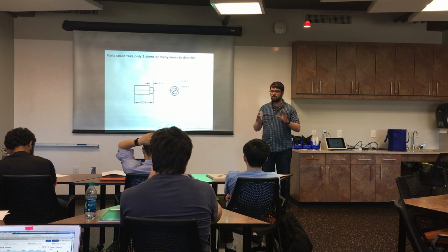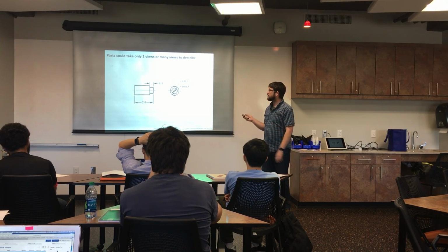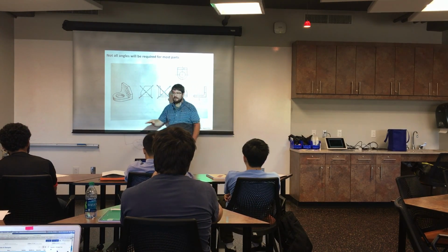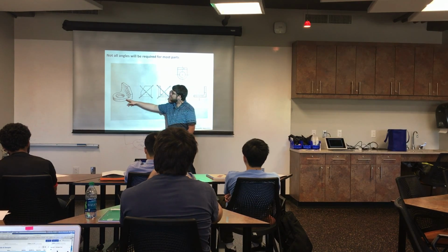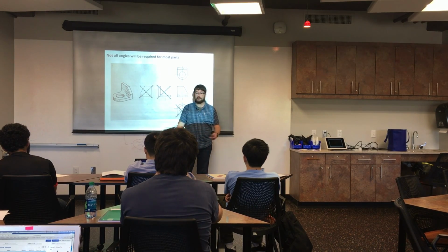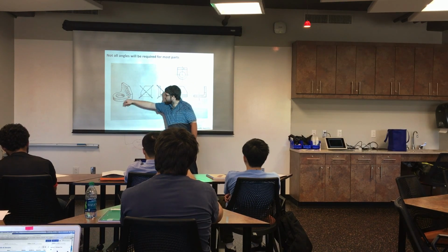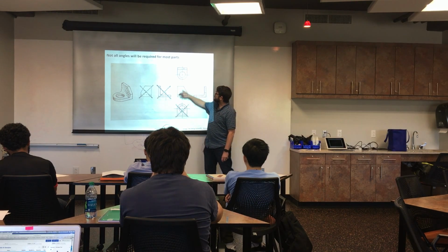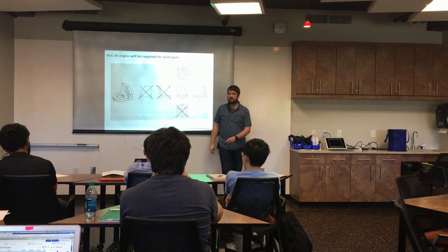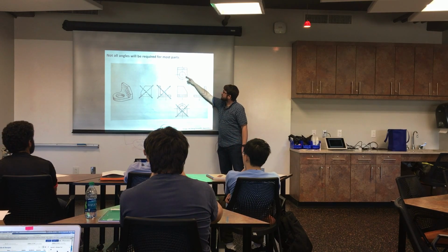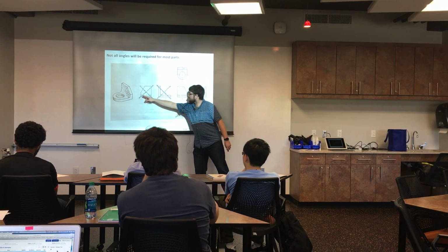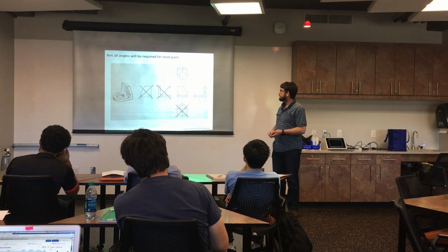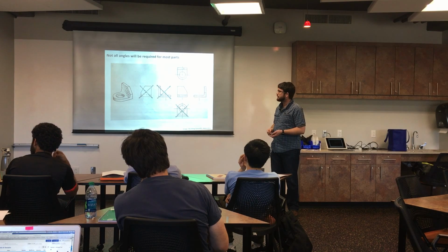Looking at drawings takes a little bit of time, especially when we start putting some of the more complicated features on. So if you look at this part, and you think about your glass box, there are 6 drawings that you could make. This is a little bracket. This is something that we could conceivably see building for the lab to hold something in. So put a screw through there, and maybe it holds something as a clamping bracket. So there are 1, 2, 3, 4, 5, 6 drawings that we could use. The most useful turn out to only be these 3, the top, the side with the plate, and then the end. You could make the rest of the drawings, but it would be a little bit redundant.